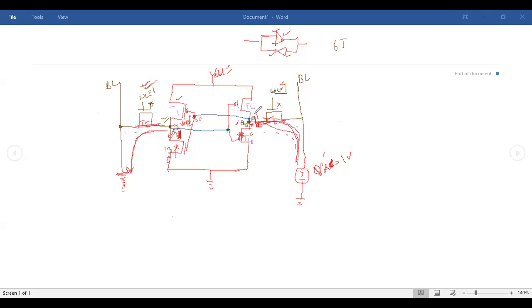And this is also supported by the fact that your Q gets discharged, means Q is moving towards 0, and this 0 will go as an input to this inverter. When this inverter has a 0 input, it will give 1 as output. So it gets two-way support. One support is from outside, one support is from inside, which is a 0.